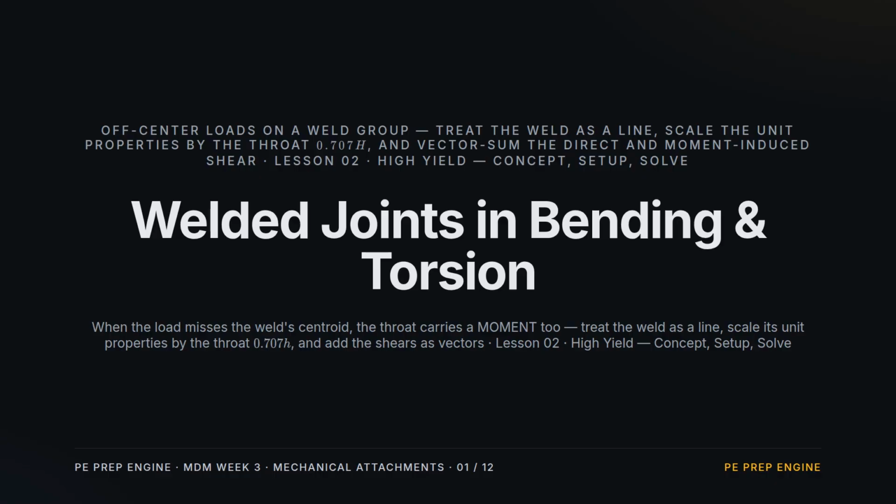Week 3, Lesson 2, Welded Joints in Bending and Torsion. Lesson 1 pulled the load straight through the weld, so the throat shear was uniform. Now the load misses the weld centroid, and the throat has to carry a moment on top of the direct shear. The trick is the same one every time.